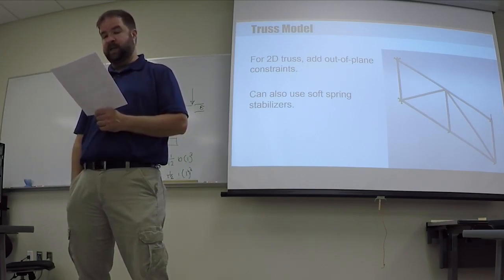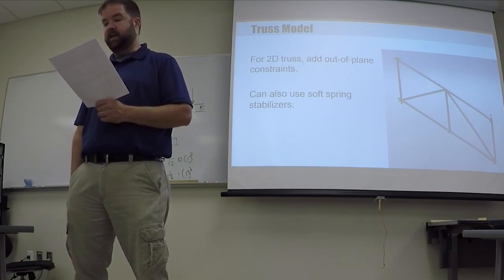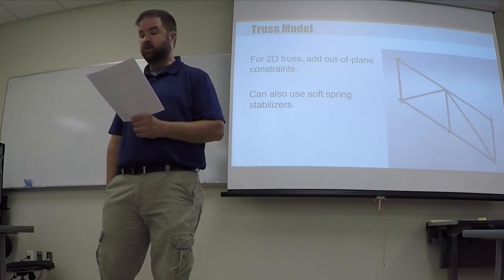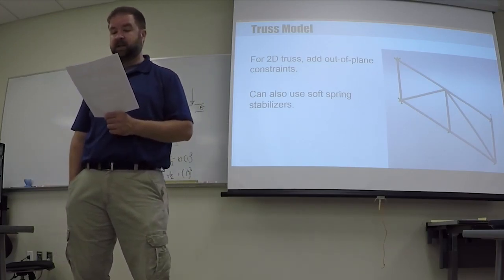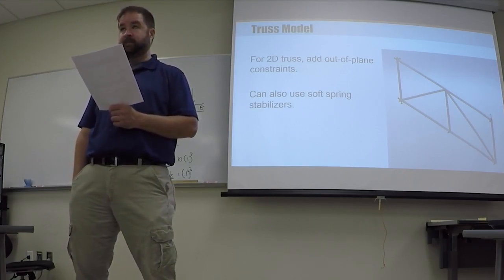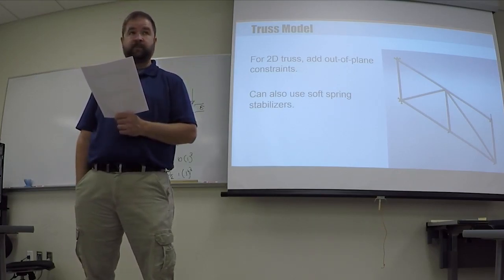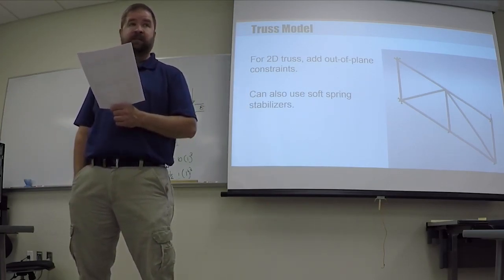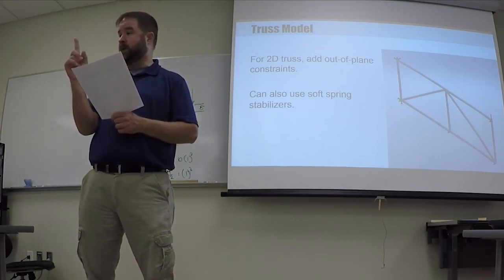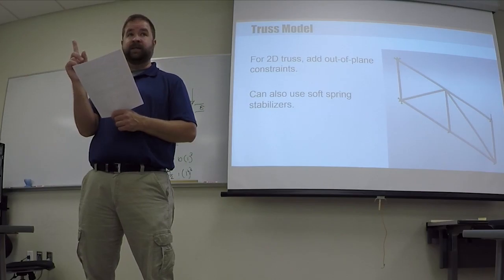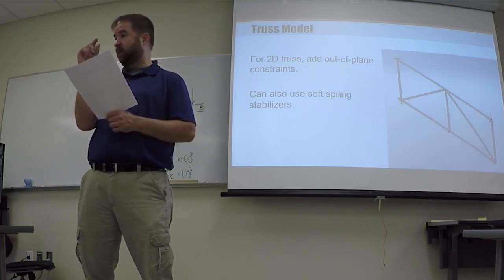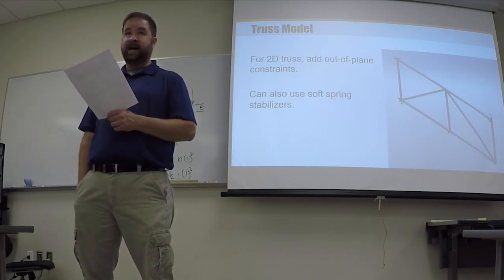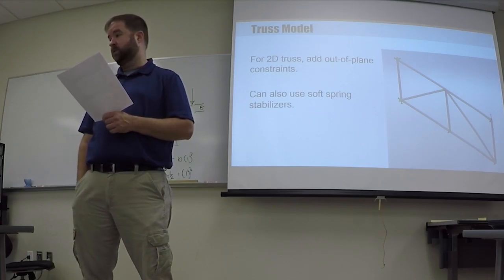All right, so here's my tapered beam. It says, create a finite element model using elements of constant cross-section using beam elements. Use 1, 2, 4, and 8 elements of approximately equal length to approximate the tapered beam. So this is exactly what I drew on the board earlier. If I'm going to represent this beam as one element with a constant cross-section, then that element is 5.5 inches wide by 1 inch tall, and it is 50 inches long. Do that analysis and see what SolidWorks tells you the answer is.